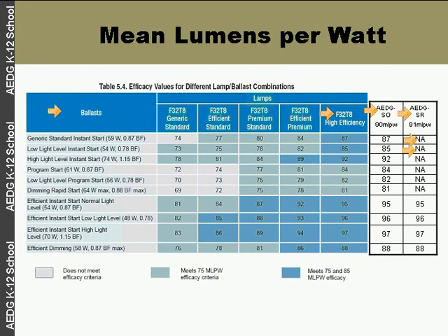They can come with an occupancy sensor either built into the fixture, or you can put them on rows down the aisles to turn the lights off. We want a T8 high-performance system, and that's basically the lamp and the ballast. They're both high performance. Or you could use T5HO technology, which is a different size lamp. It's a 5/8 of an inch diameter lamp. It works very well for high ceiling applications.